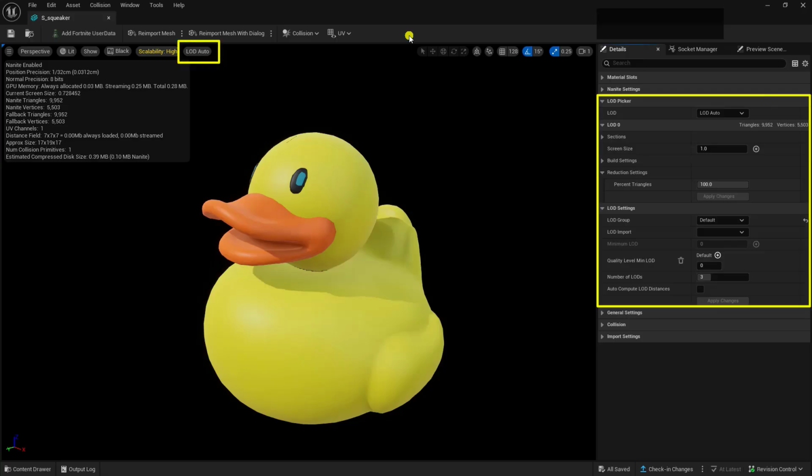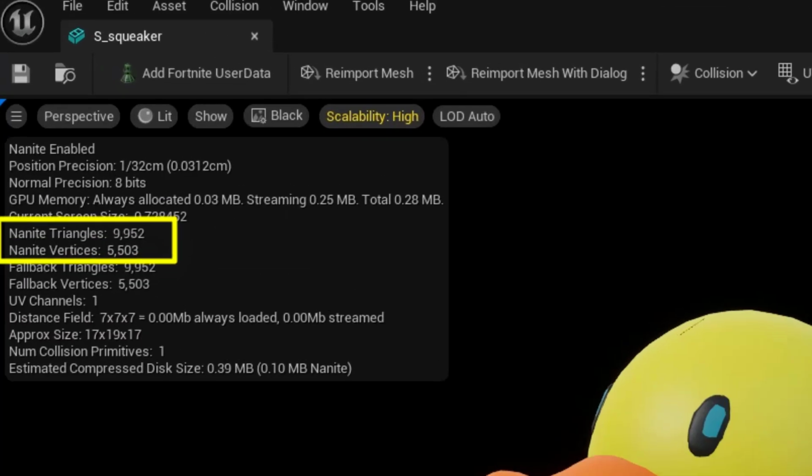To be able to control the LOD, or level of detail, of an object inside of UEFN, the vertex count must be less than 50,000. If it is more than 50,000, the engine will automatically control the LODs, giving us very little to no control over how our objects are seen in game.